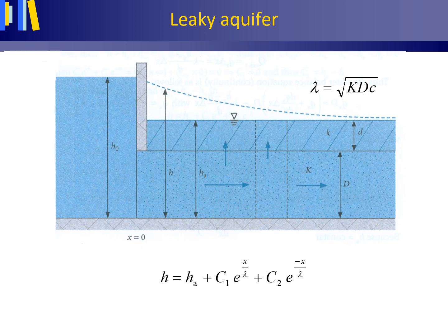For both finite and infinite polders, a finite polder being a polder with a fixed boundary condition to the right, we will see an example of this slightly later on, the hydraulic head distribution with horizontal distance x in the aquifer, thus the potentiometric surface shown as a dashed line in this figure, can be determined from the water balance of this column, or rather rectangle of the subsurface, and then described by the following equation.